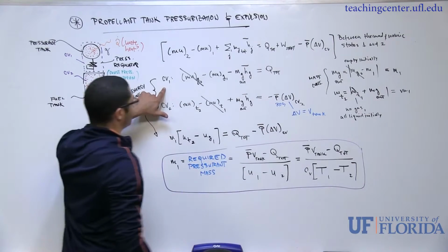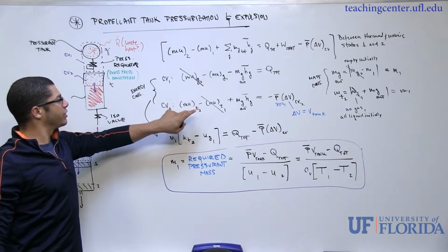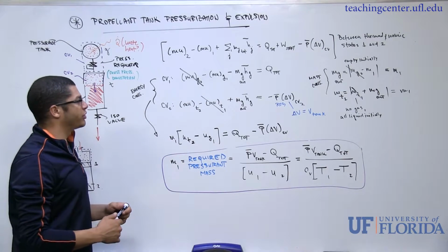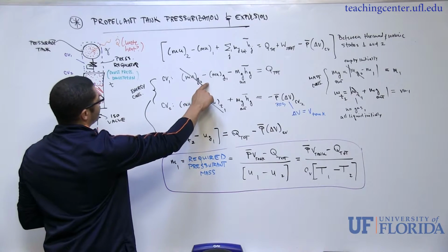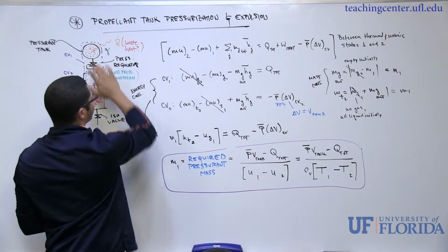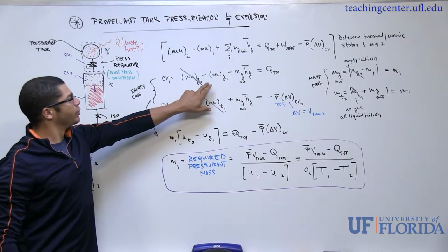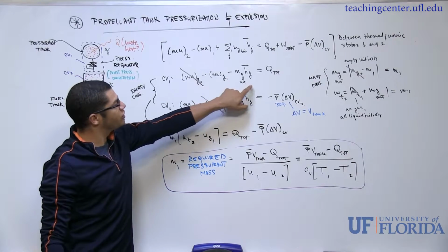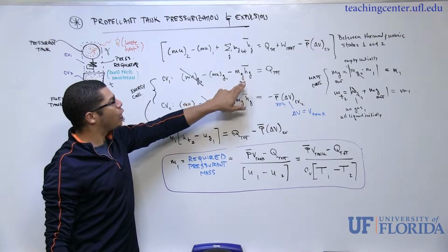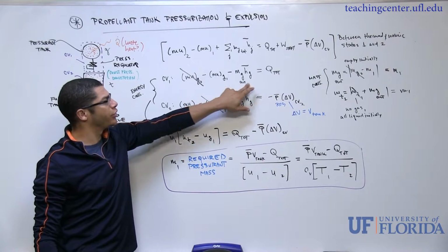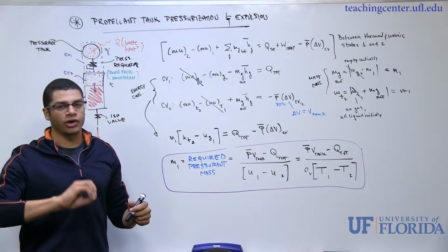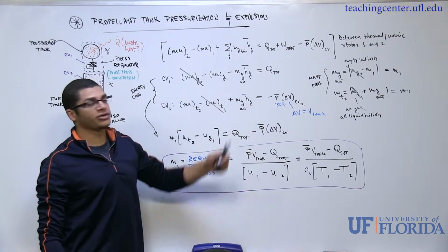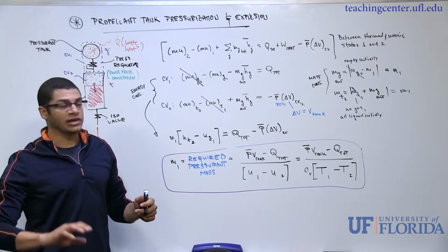And so that's what I've done here. For control volume 1, and CV2, you can neglect these terms I've crossed out, and I'll keep them down initially until I've explained why they're gone. But we've got the internal energy of the gas in the pressurant tank at state 2, minus the internal energy of the pressurant gas in the tank at state 1. Now I've got minus just one mg out hg bar. So this term right here represents all of the mass of pressurant that's left the system over the time interval that we're considering, times the average specific enthalpy of the pressurant as it leaves the system.